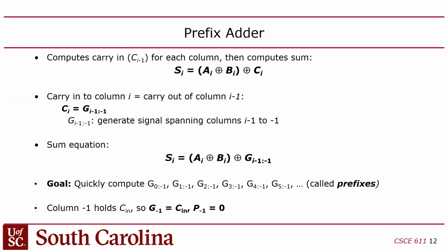So you would always have these 4-column chunks for P and G. With the prefix adder, they don't have that same restriction. With the prefix adder, they calculate generates and propagates with arbitrary ranges of bits. And also, they consider column -1, or I should say the generate -1, just to be the top-level carry in, by convention, okay?